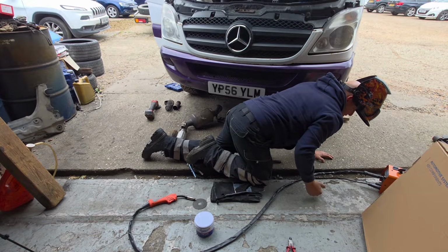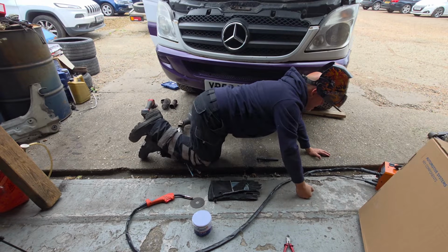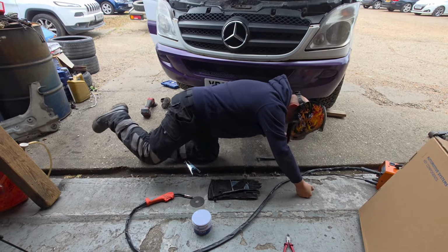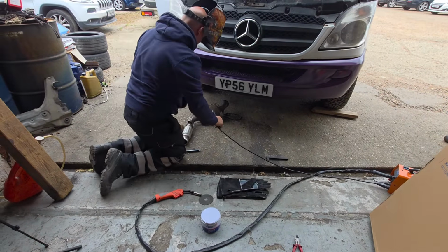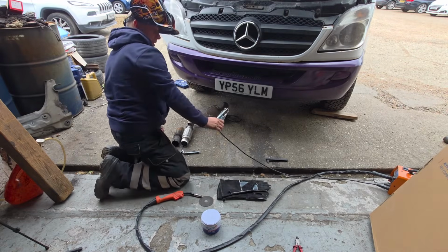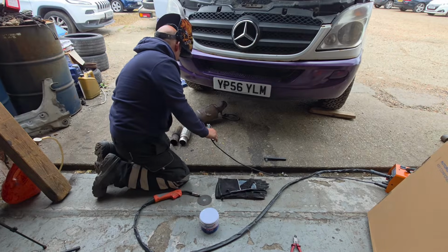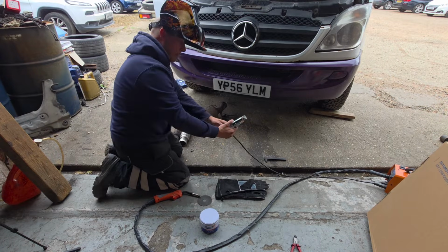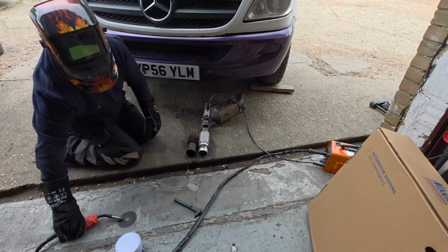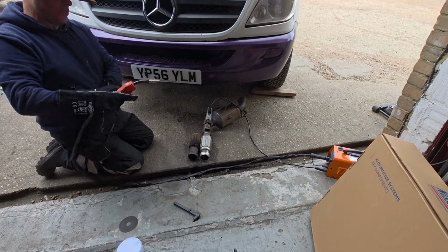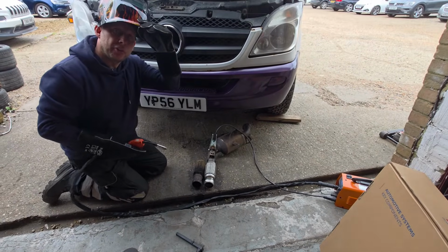Yeah, we're set at 150. We're on the 0.8 flux core wire in MIG. We're at 151 actually. So, first problem, Dan. We're going to need to bring this forward to enable us to put the earth on. But I don't want to mess up your dimensions. We are just going to tack a weld round on here and see what we have got going on. Make sure you don't look with your eyes.